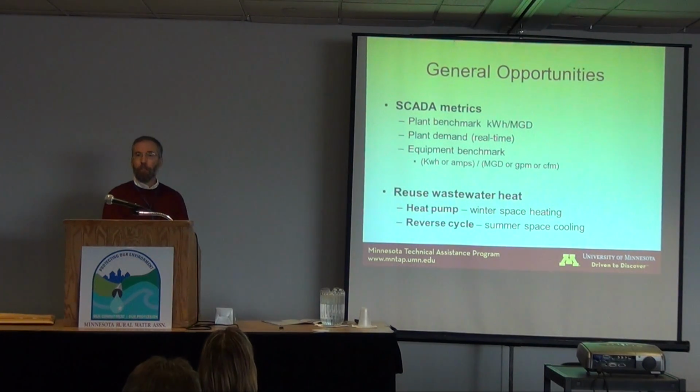If you've got a demand charge on your electrical bill, I think it would be useful to track plant demand on a real-time basis. There are some plants that use that to lower demand charges, and essentially be careful about which equipment they're running at the same time, and plan their operations to avoid peaks in demand, and essentially load shift.